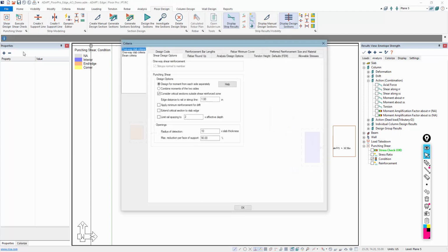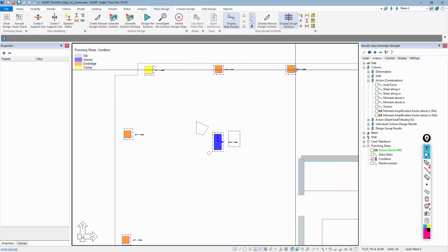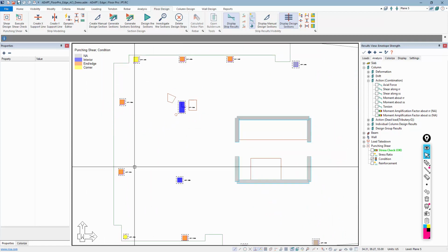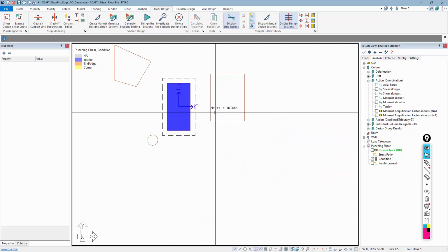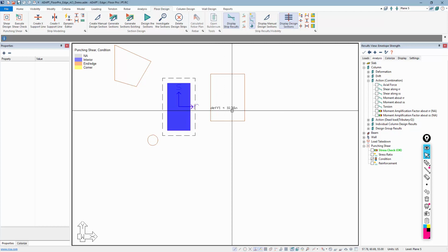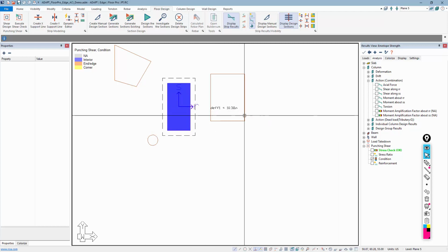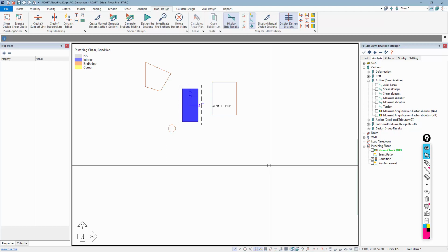And coming back to the shear design, we did not extend it to the slab edge. So this is a pretty conservative check for those columns on the perimeter where we have this little cantilever hanging off the side. But this just kind of color codes the critical section. The effective depth is reported. This is just the first critical section's effective depth, 10.38 for that first critical section. So this just shows really the first critical section from face of column.